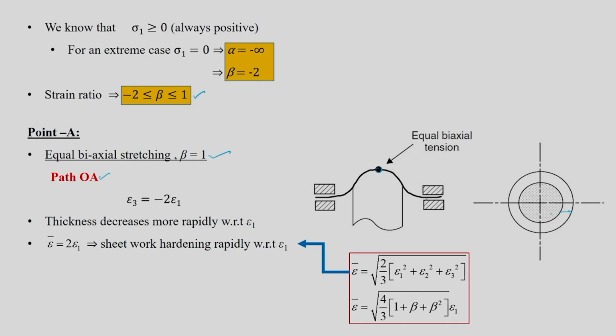Like there is a sheet which is kept in a blank holder, and the punch is getting displaced here and your sheet is getting deformed here, right. So, this is your height of deformation, this much it has deformed, and you will see the beta is equal to 1 situation somewhere in the uppermost portion, that is the pole region. That element, if you put a circle on that particular location, is pulled equally in both the directions. So, it will be like this.